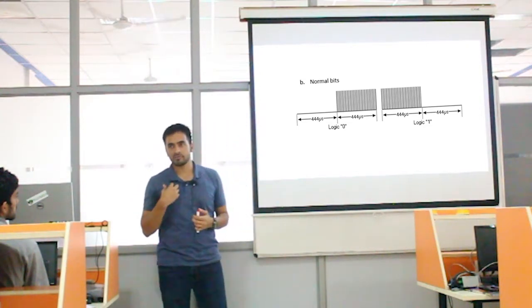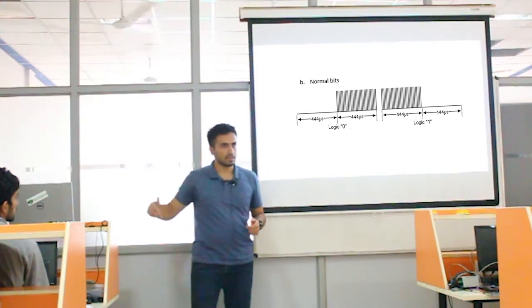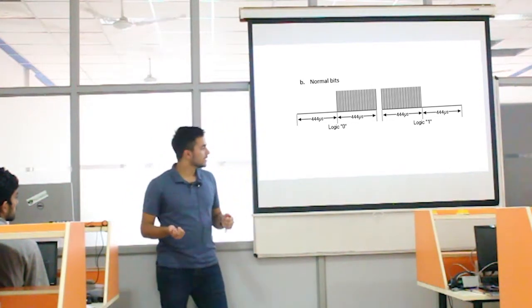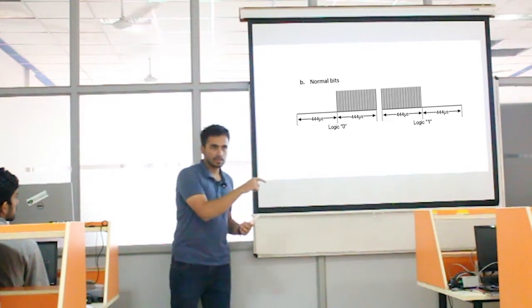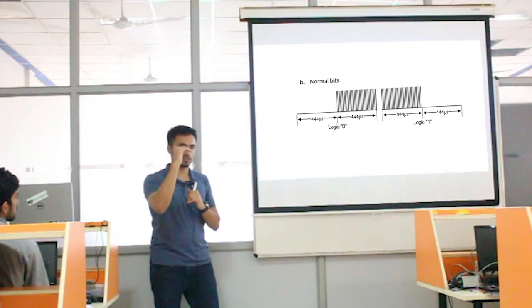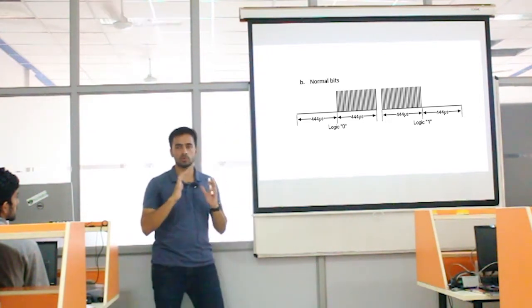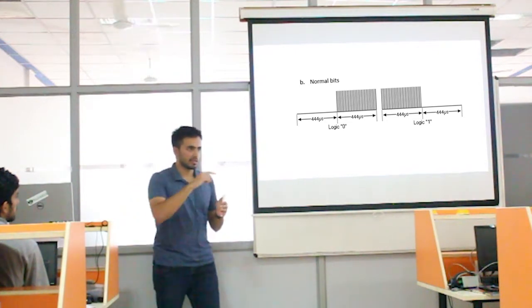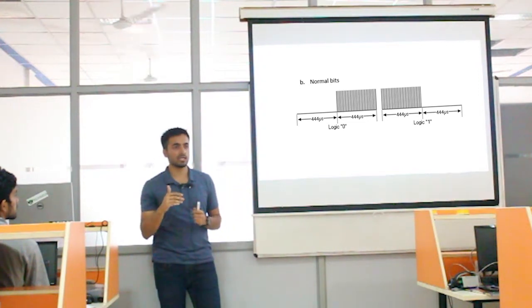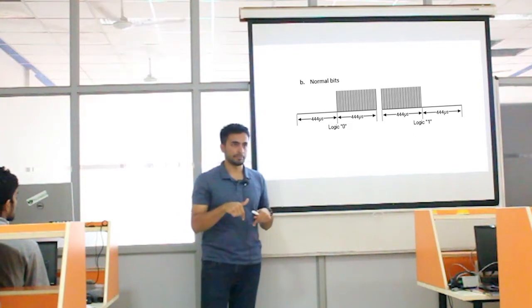But usually what we write is software delays, right? We pass a function, we run a while loop till that count, and that is not as accurate as this. You can't get 889 microseconds with that. So to generate this, first I have to have a timer which switches on, switches off my GPIO for a very specific time period. So if I want to transmit at 38 kilohertz, the time period is going to be 1 by 38,000, and it's going to be off and on in that time.